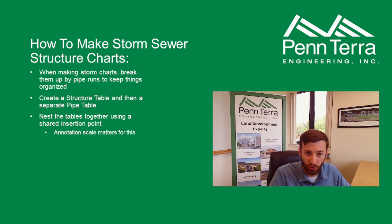And then we'll show it, but whenever you create these, you want to make sure you have the same annotation scale that you're going to make your viewports in the plan. Typically this is 50, so it would be the same as when we make a legend or something like that.